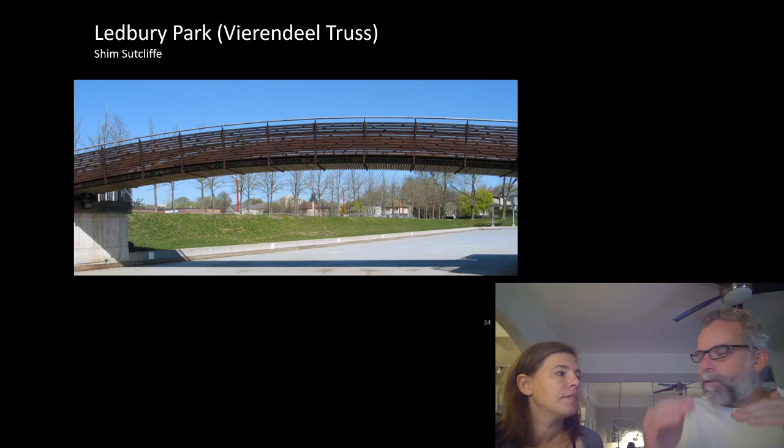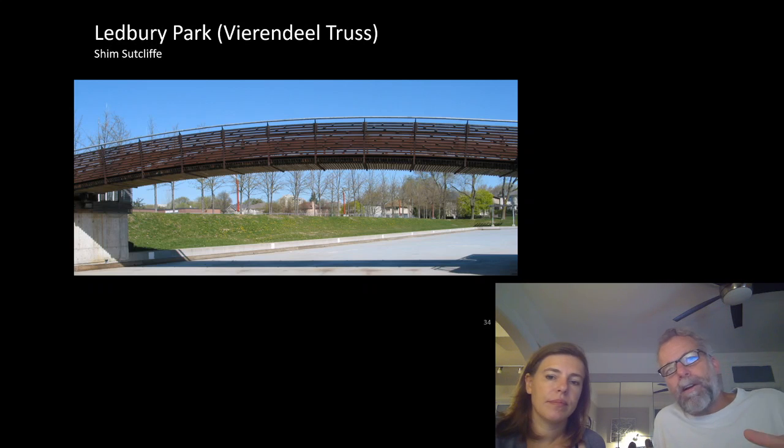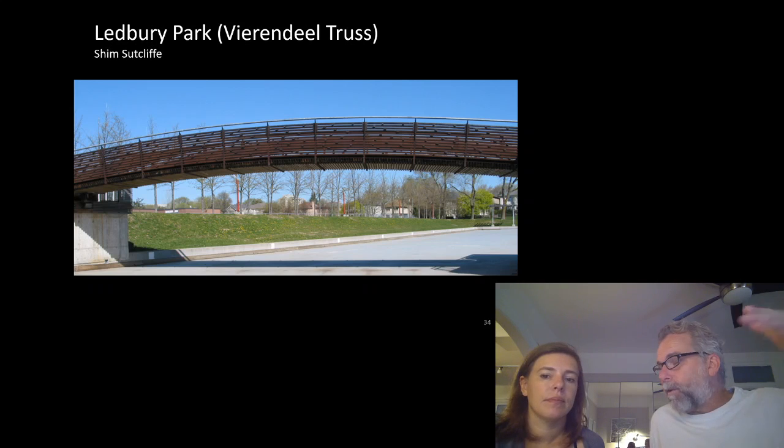You know, the building code and the bridge code have a lot of parallels. Like the forces are very similar, and the guard forces, the standard guard height. But there's a few distinctions. Climbability may be one of them. If you're riding a bicycle across it, you need a taller guard. That's another. So I think it's a 1.5 meter guard instead of a 1.07 meter guard.